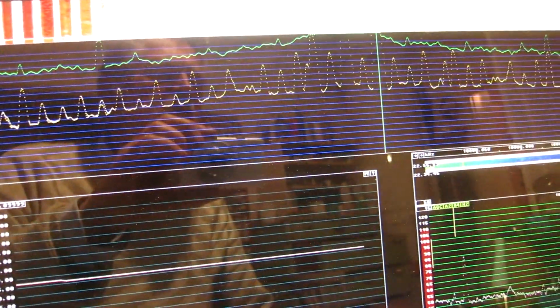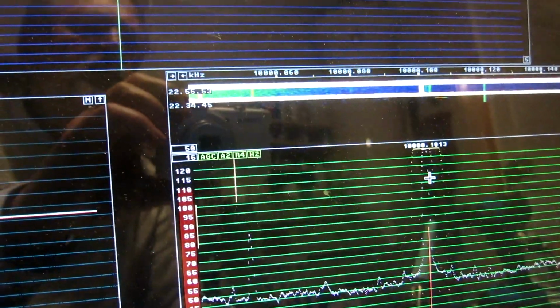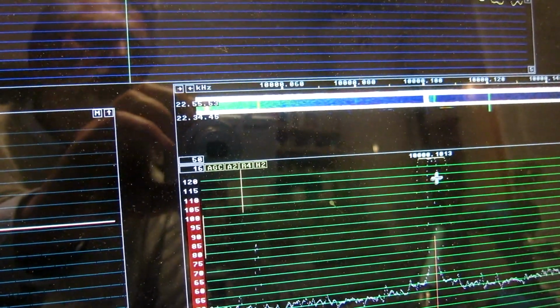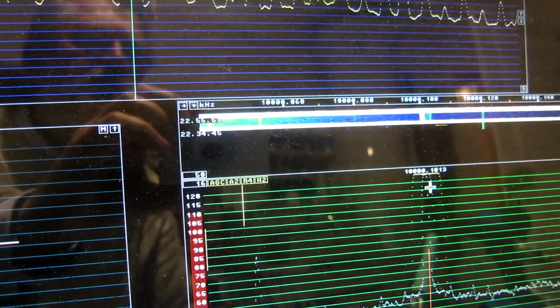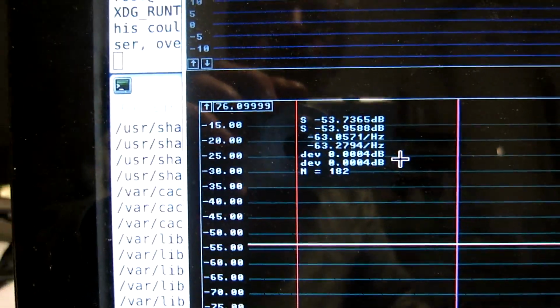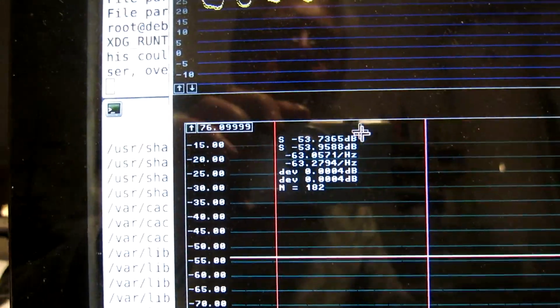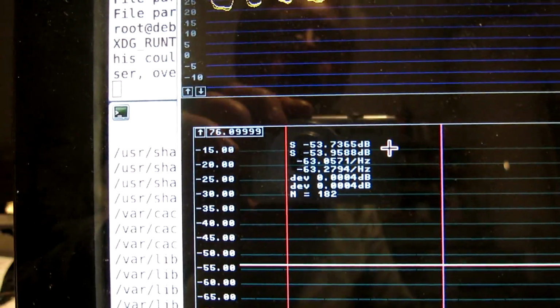The injected signal at 100 Hertz, about 10 megahertz. It's now at -53.7 because I reduced it by 3 dB and there is some loss because of the crystal.